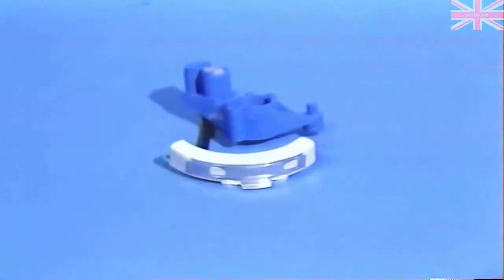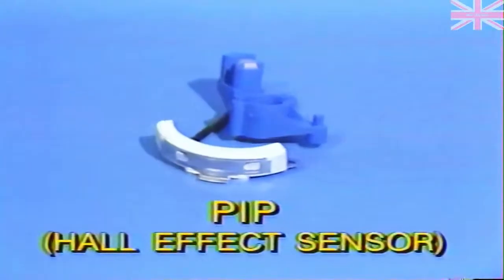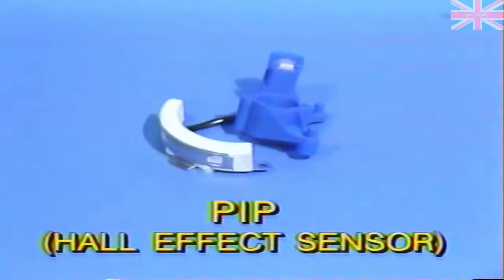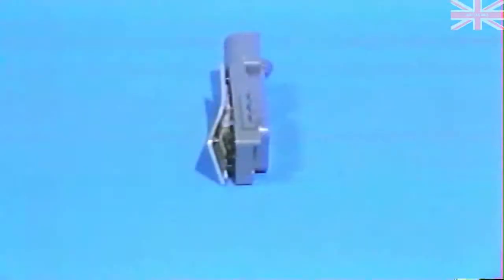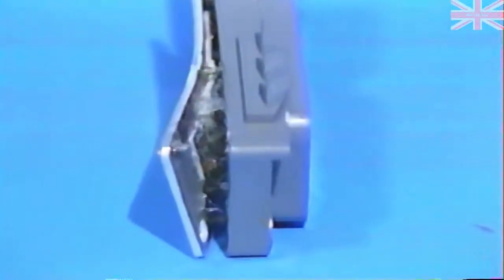The late thick film ignition assembly works with a Hall effect sensor or Hall effect pickup in the distributor. Earlier versions use magnetic pickup assemblies. A very common complaint on early thick film systems happened when the plastic housing of the ignition module itself separated from its base plate. This caused an intermittent no-start condition.